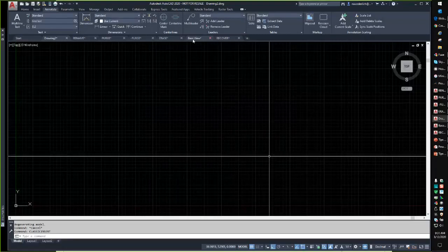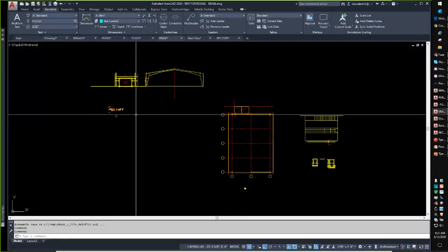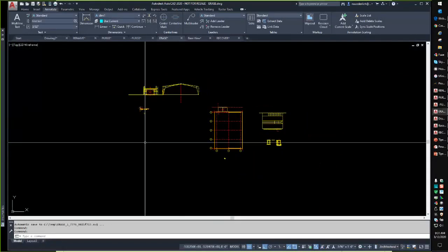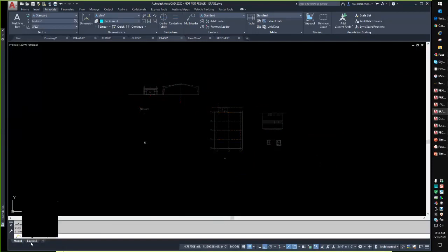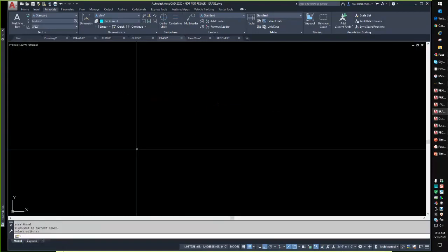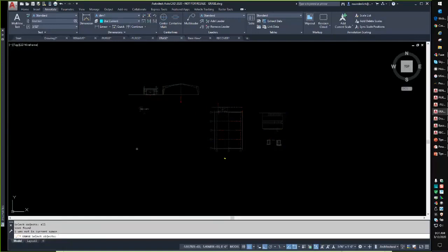So that's that. And now we're going to talk about this. This is one of my favorites. This is one of the erase alls. So what you have in here, it's a fairly simple drawing, right? I'm going to invoke E for erase, and I'm going to type in the word all. And you'll see that it says there were 1,165 objects found and one was not in current space. That's because layout always has one. Okay. And I hit erase all. And then I hit R to remove the objects. And I just simply do a window over the objects that are visible.